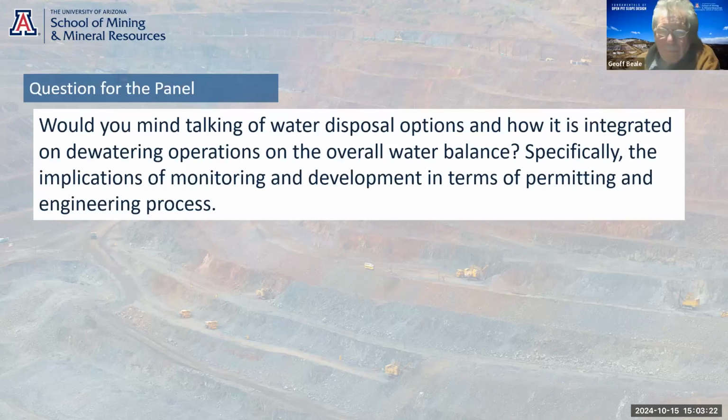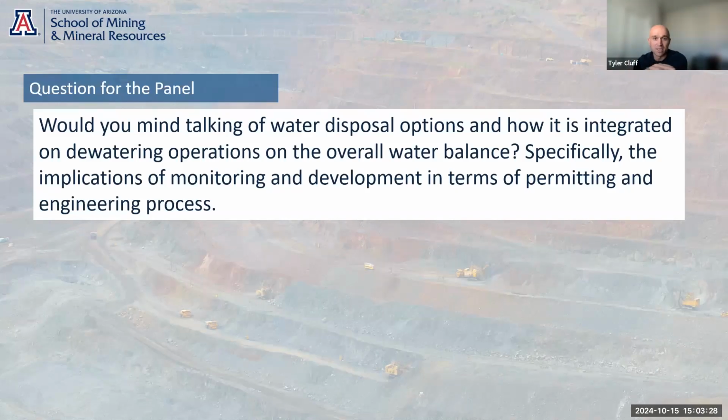Yeah. I think that design component, in linking the water balance and sustainability, Jeff, what you were just mentioning, I just reiterate, I'm working on a site where, with their current plan, they're going to experience both a water surplus and a deficit inside of a 7-8 year period, and an element of that is because of an over-aggressive dewatering program.